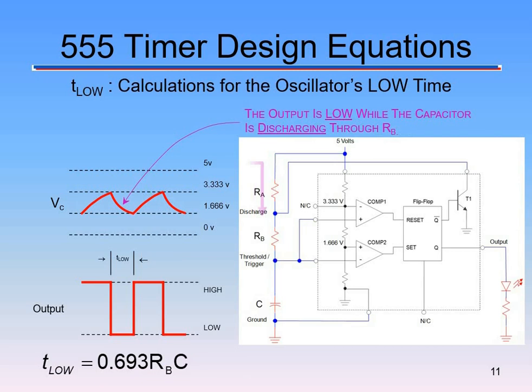What's highlighted in blue is discharging the capacitor. We've flipped a switch now, and we're taking this violet path. We're going through the transistor now, discharging, and we're gaining an output of 0 instead of an output of 5 or whatever the voltage is that we have on here.